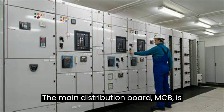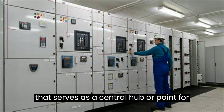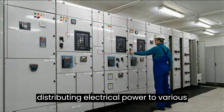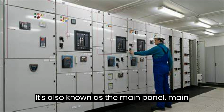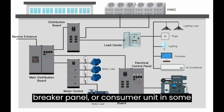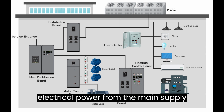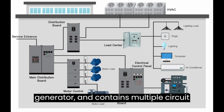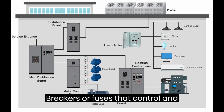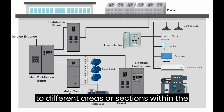The main distribution board, MDB, is a key component in an electrical system that serves as a central hub or point for distributing electrical power to various circuits within a building or facility. It's also known as the main panel, main breaker panel, or consumer unit in some regions. The MDB receives electrical power from the main supply source, such as the utility company or a generator, and contains multiple circuit breakers or fuses that control and protect the distribution of electricity to different areas or sections within the